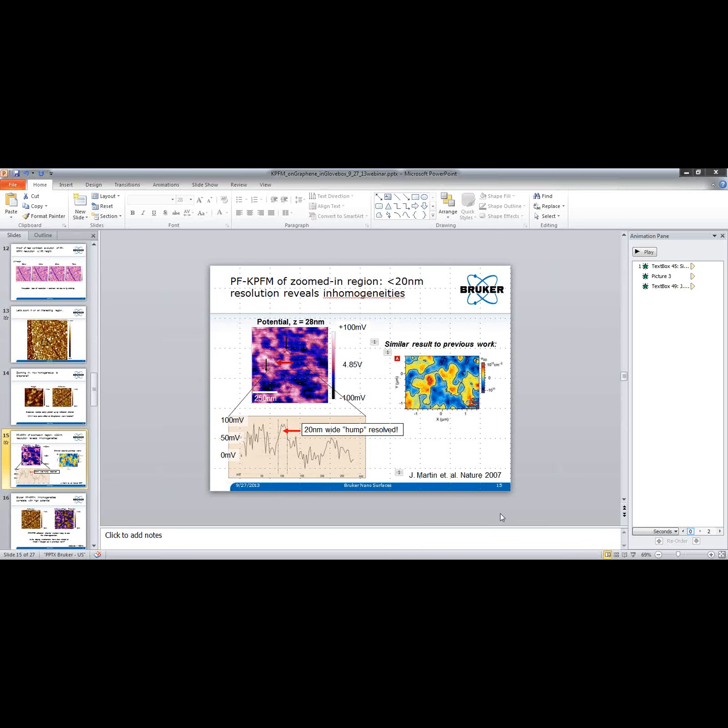There are other issues that creep in if you try to put boron nitride. You can put other dielectrics, you can evaporate or sputter other dielectrics, but encapsulation of the graphene is actually a very interesting and active area of research. People are looking into various options, but if you put too thick of an encapsulation, a perfect insulator won't screen the charges.